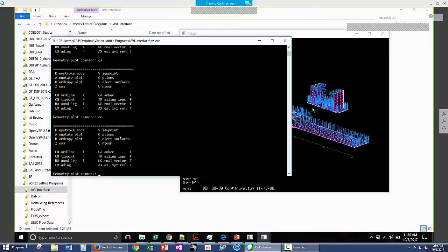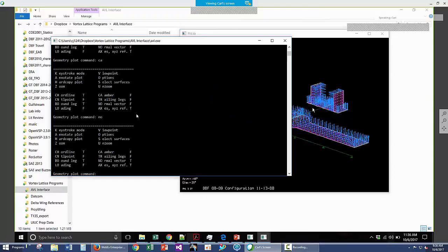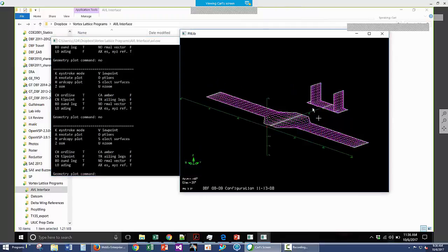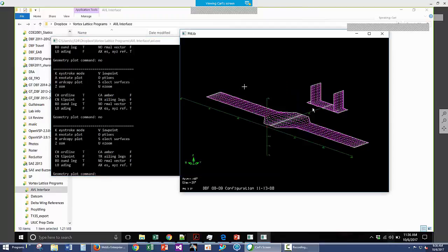I can look at the normal vector, and this is the normal to the camber line vector, where that is defining the no flow through the surface condition in order to solve the strengths of all of my vortices simultaneously in order to get a closed solution. So I can at least visualize this, which is basically just the camber line, only now the normals to it. There's many other things you can do here in terms of changing the angles, etc., but it's very awkward because it's a DOS interface. So you can play around with those if you want to, but this gives you a starting point.